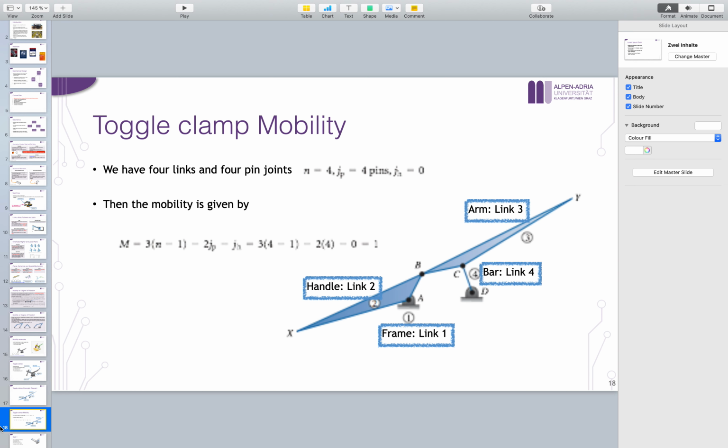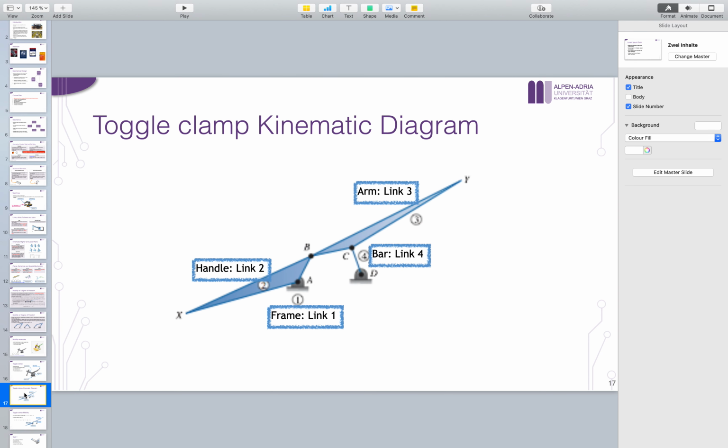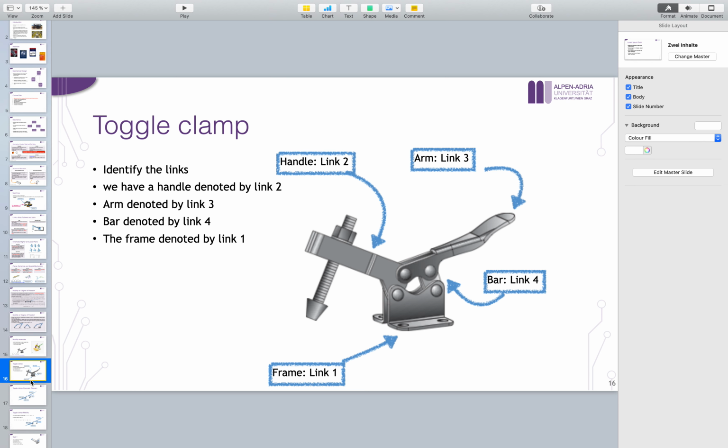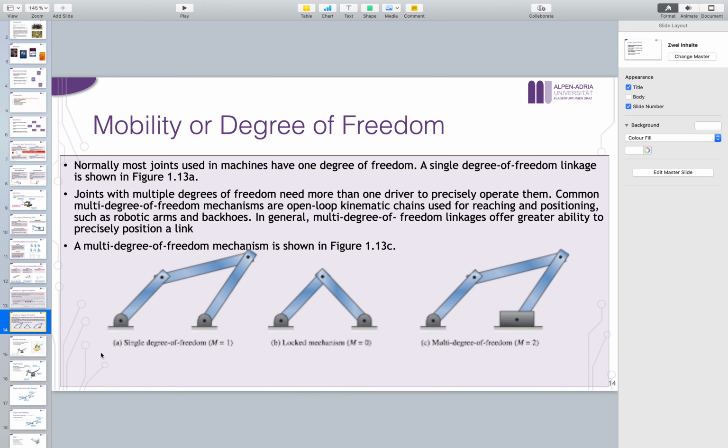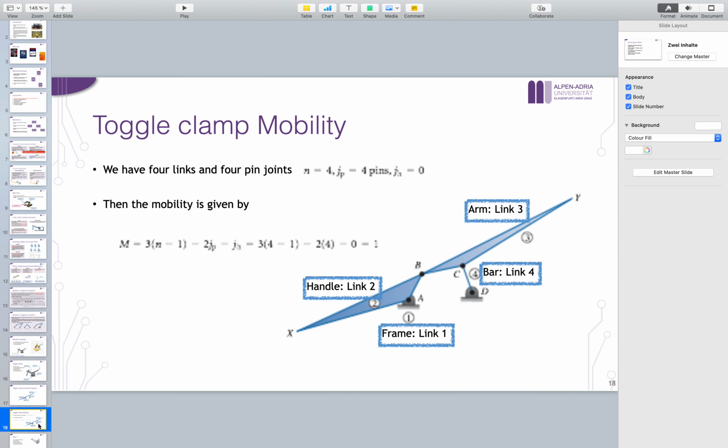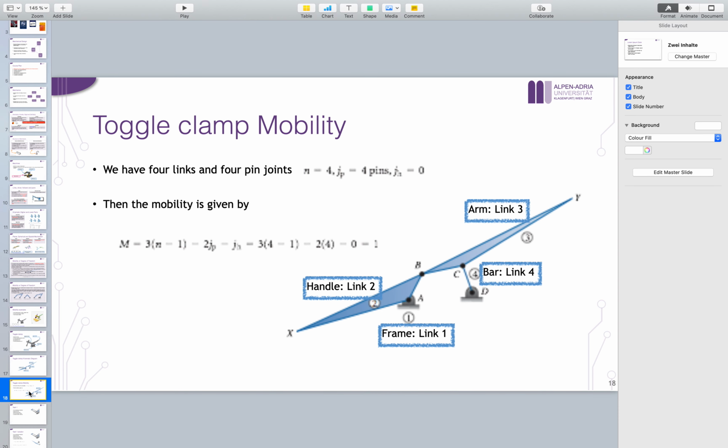So I directly found that I was wrong when I said 12, because whenever you look at connected mechanisms, by definition the mechanism has 1 degree of freedom or less, so this is either 0 or 1. We found it's not locked, right? Because it can actually slide, go up or down. This is why I paused when I said 12, because 12 would mean we have more degrees of freedom, but we don't.